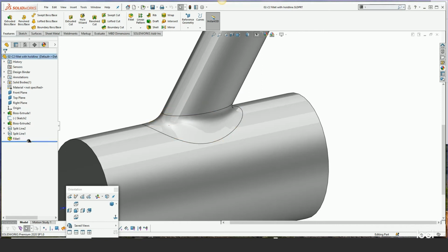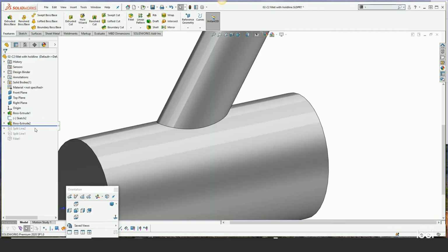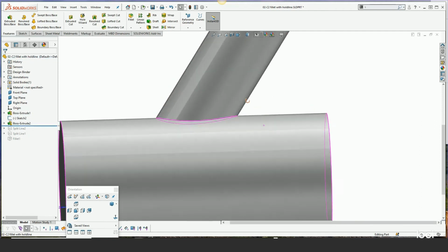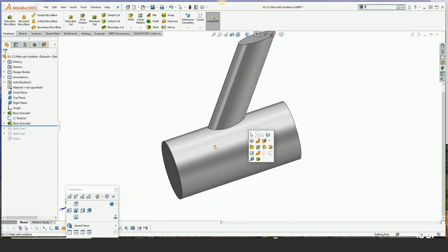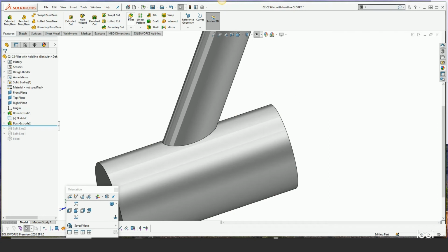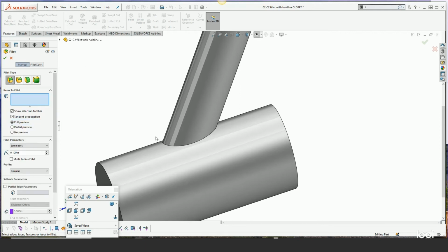And let me just roll forward here and talk about a few things. Here we have an intersection of this strut with this other strut, and we need to fillet it. Now, you might be tempted to, and it's completely fine to, put a variable fillet between these two. If we put a constant fillet, I can show you what the result of that is.